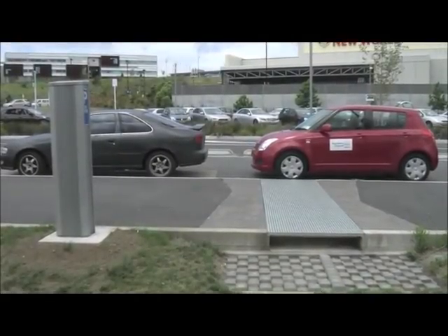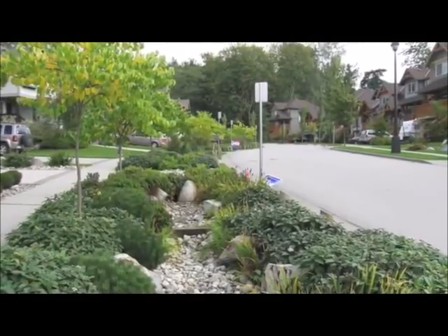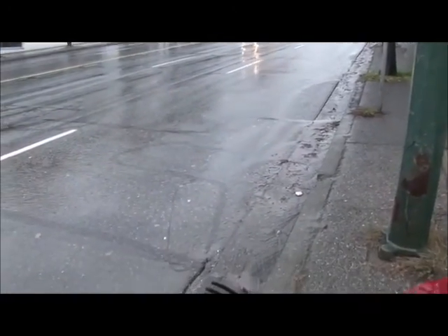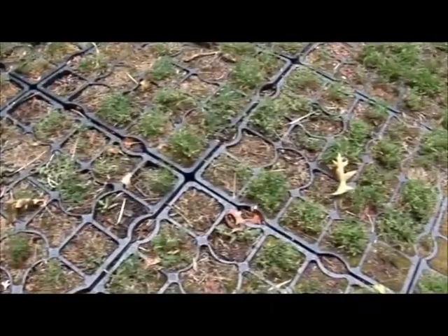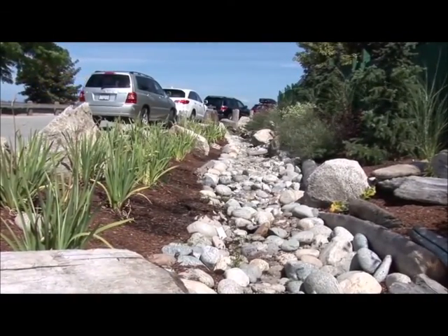Innovative stormwater management designs, or low-impact development at the neighborhood scale, can delay and reduce surface runoff dramatically. They can also reduce contaminants, which under traditional designs are conveyed directly into streams. These low-impact development examples are still not mainstream in many municipalities, as the initial capital costs are often higher than conventional stormwater systems. So the more green infrastructure we can put in place now, we actually strongly believe we're going to save a lot of money in terms of future costs in dealing with some of these issues, erosion, flooding, and other kinds of things like that.